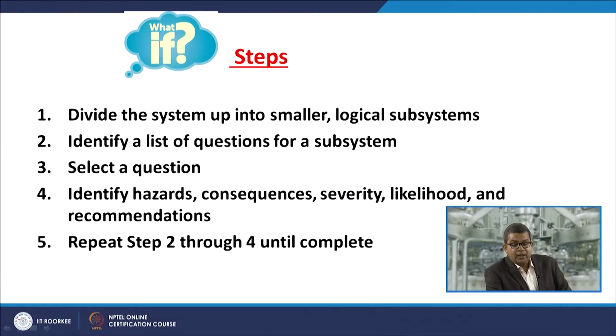So how can you frame the system? There are various steps you need to follow to carry out this what-if analysis. Divide the system into smaller logical subsystems. If you divide the system into various smaller logical subsystems, then the quality of the response would be on the higher side. So you need to identify a list of questions for the various subsystems, right? That depends on your knowledge, your competency.